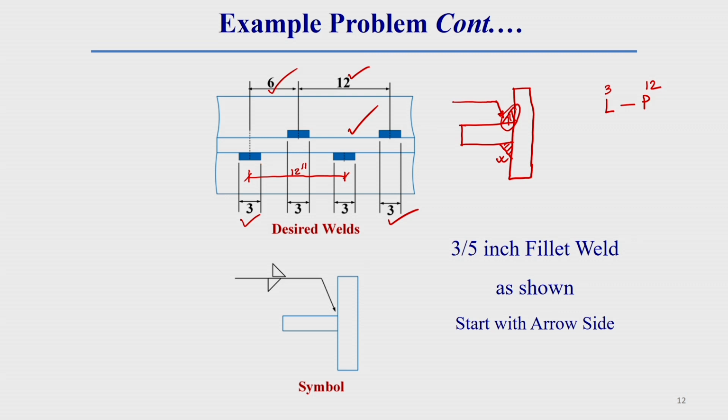That is why generally here we should put the weld symbol, generally one starts a little bit ahead, so the other side is this side. So, we see that this other side weld started before the first weld, that is why you have to put this weld symbol a little bit ahead of the arrow side weld symbol. So, here what will be the parameter?